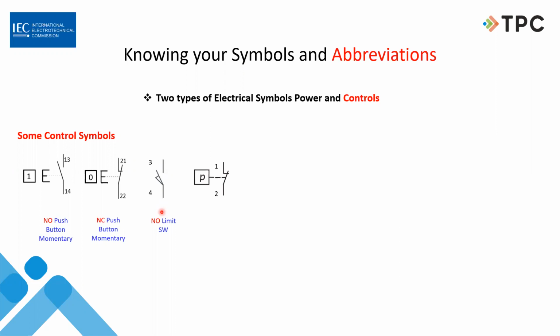Here's a normally closed contact. So back to our 1 and 2, we keep talking about this 1 and 2. And this is a pressure switch. It's got a P. So you're going to see a lot of contacts that are similar, but they put a different letter in here indicating the different type of device. This is a pilot light for IEC. In some places, you might see a letter by it or in it. Most of the time it's like this, and next to it there's the words red, yellow, or whatever. But typically, that's all you're going to see on a pilot light.